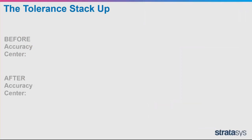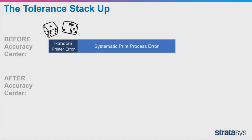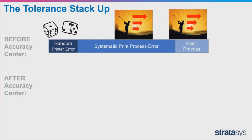So how are we making your parts more accurate? Well, before Accuracy Center, when you'd print, there's a certain amount of random printer error, but a bigger amount of systematic printer error. Thermal effects, where it is in the tray, your geometry. But the interesting thing about that is it's not random. It's consistent, like wind on your tee shot. And if the wind is always blowing to the right, you can angle your tee shot to the left and correct for it. There's also post-processing error, which is mostly thermal effects, but that's also not random. That's also like wind on a tee shot. And then there's a little bit of scanner error itself.